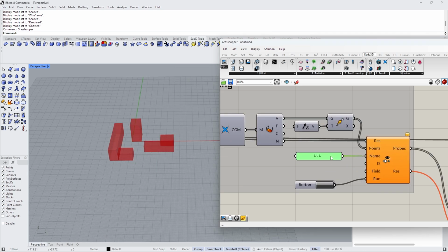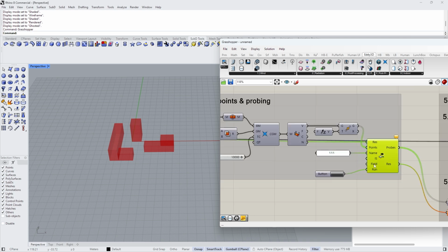Now, what's important to say here, before we run this, I don't know how that's called, probing, what's really happening is that OpenFOAM has run its calculation in the wind tunnel based on the setting and grading inside. It chops the whole thing in segments, in cells, and each cell will be tested. It's just how I imagine it. The probing basically just makes something visible which is already calculated. And as we said before, the U is related to the wind direction. U is basically the velocity in meters per second, and that's our output.